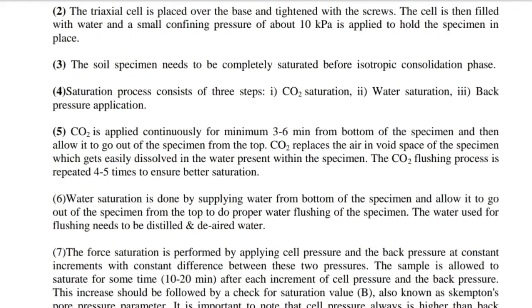3. The soil specimen needs to be completely saturated before the isotropic consolidation phase. 4. The saturation process consists of 3 steps: 1. CO2 saturation. 2. Water saturation. 3. Back pressure application.